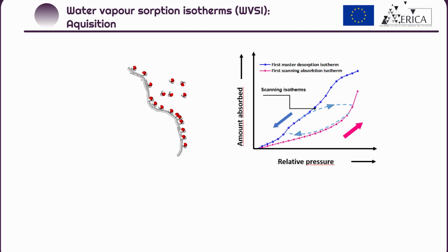In moisture sorption, we consider this vapor-solid interface. Now the solid is called the adsorbent and the vapor, which is capable of being adsorbed, is called the adsorptive. The fluid in the adsorbed state is called the adsorbate. Adsorption, the surface phenomenon, and absorption, the volume phenomenon, together are called sorption, or absorption sometimes, and the reverse is called desorption.